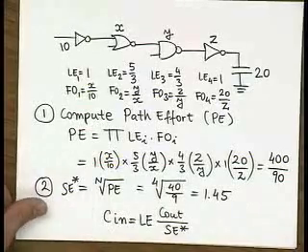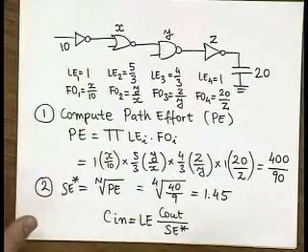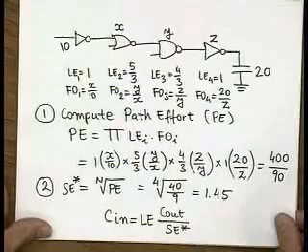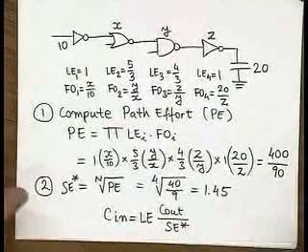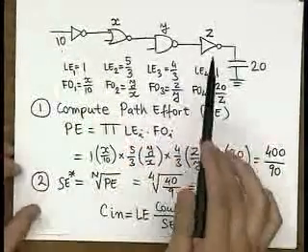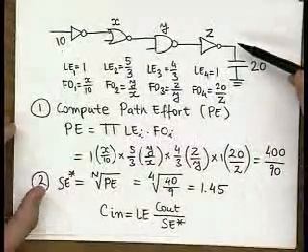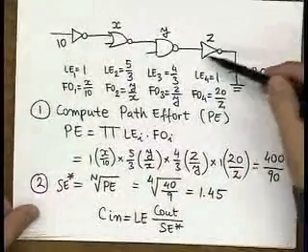So let's now figure out optimal sizes. We can start either from the input or from the output. We typically work backwards and calculate Z and then go back through the gates.